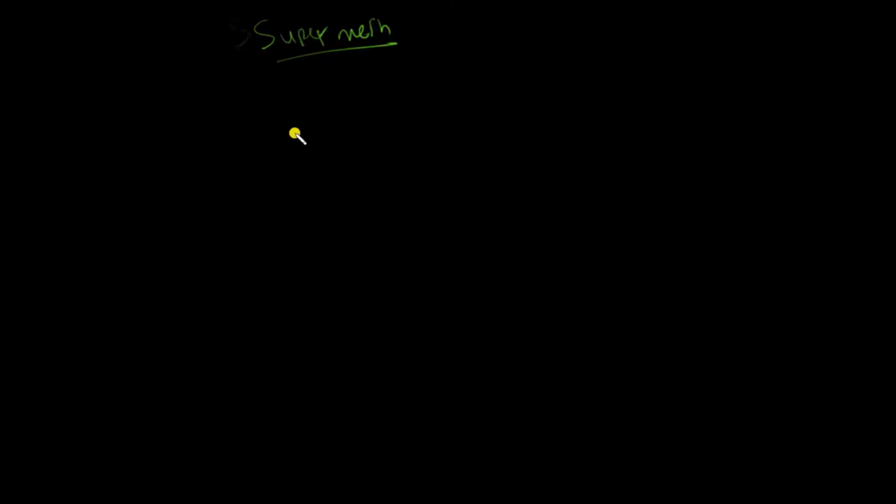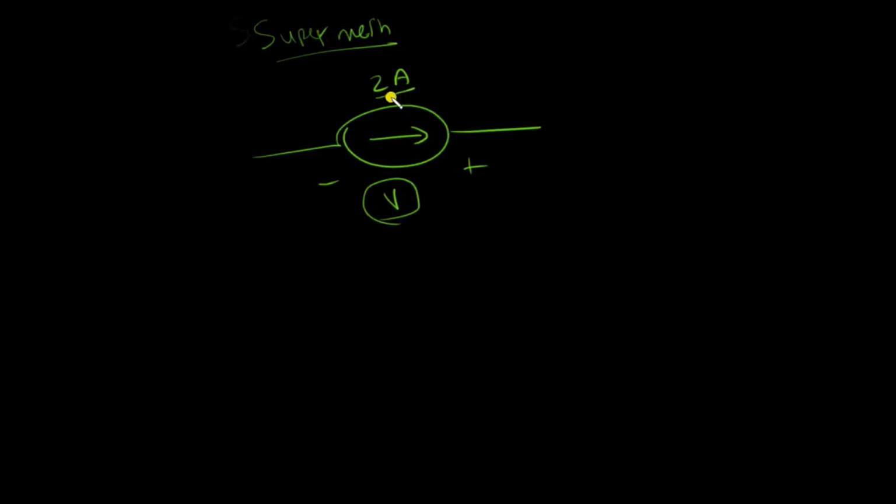As you can recall from the videos of the sources, the main characteristic of a current source is the current. Whatever the voltage across this element is, and there would be a potential difference across this element, because all electrical circuit elements have a potential difference, this voltage can be anything, and the current would still be the same. This is a problem when you're applying the KVL, because if you encounter a current source and you're just moving clockwise in the loop, you won't know what the voltage across that source is. So you need another concept of deriving the KVL equations. Let's look at an example and apply the super mesh analysis.